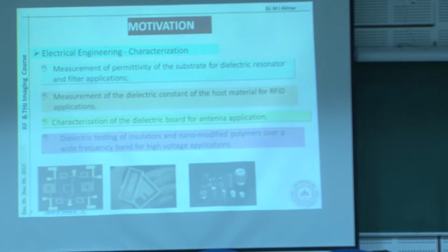In this case, it is very important that you measure the parameter at that frequency, because if you do everything right and you still have a difference of 5 to 10% in the result, you don't know what to do. The reason could be that you are taking an incorrect value of the permittivity, and without the correct value you cannot do any analysis, because any software, CST, HFSS, whatever, requires you to give the parameters. So whatever planar circuit you want to design, the substrate is dielectric, and it is better to measure its property at that particular frequency. That will give you more confidence in the design.